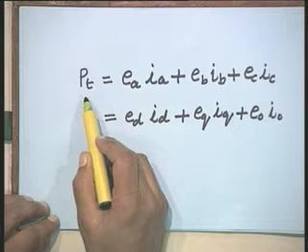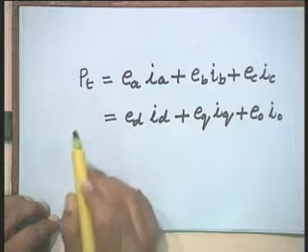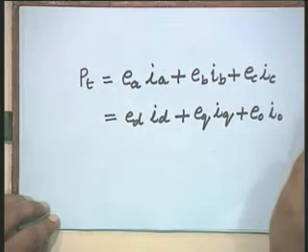Instantaneous. But what is average? The average and instantaneous become equal. In a three-phase system, the total or average power is constant. Not what instantaneous power we calculate. This sum will come out equal to the average power.